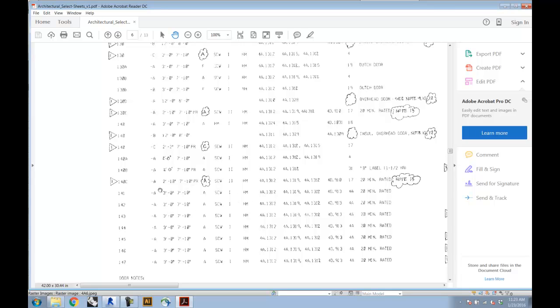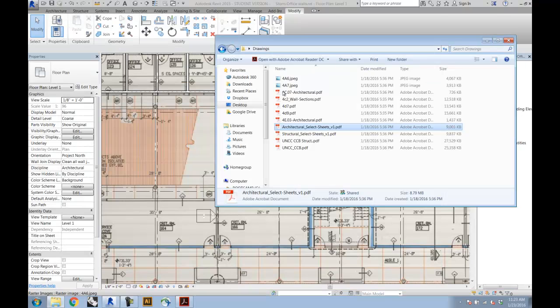It's relatively typical for the 3 foot opening, but the 7 foot 10 is quite high for a door. Typically, they're going to be at like 6'8" in residential, maybe 7 foot in a commercial project. So 7'10" is quite asymmetrical. It's linked to Gwathmey's desire to have everything on the 8-inch module. Even when you look at the doors and the door frames, they all align with the CMU in the building. So this door type is what we're going to start to adjust for.